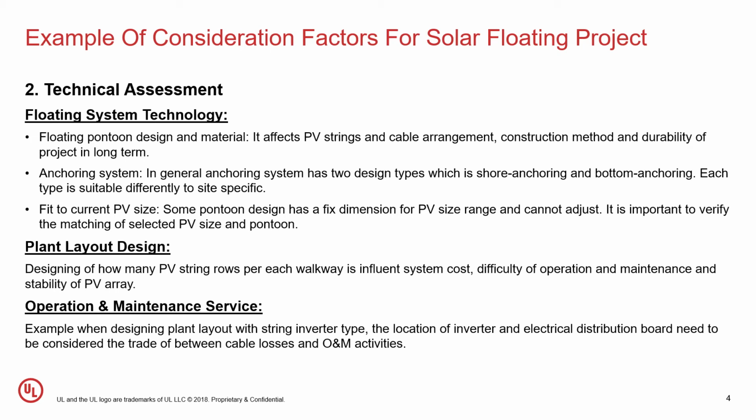Apart from the technology is the plant layout design. I will narrow down specifically to the walkway, because some pontoon suppliers have a range of options for you to select, like 4 PV strings per walkway, 2 PV strings per walkway, or 1 PV string per walkway. So you have to balance between the project cost and ease of O&M service activities.